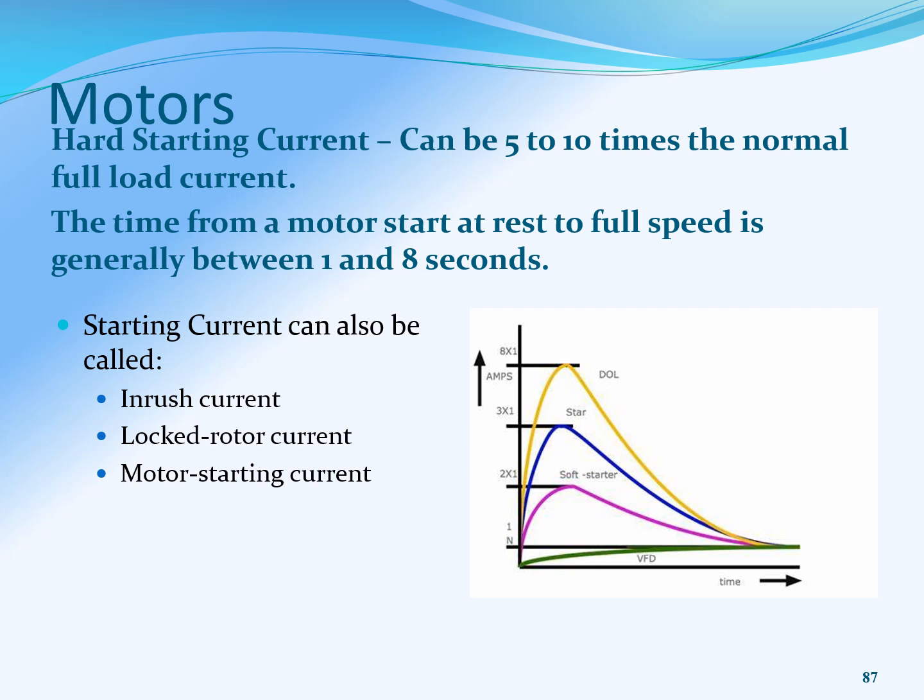That starting current is also referred to as inrush current, locked rotor current, and motor starting current. It's really important that you take these things into consideration, because you can actually damage your motor by not applying enough current or applying way too much current.